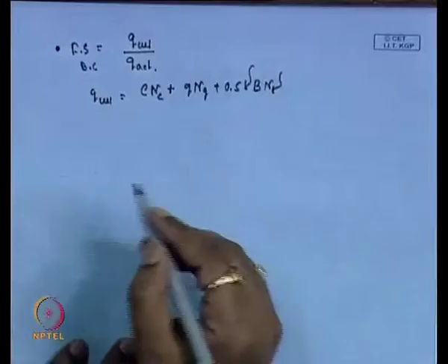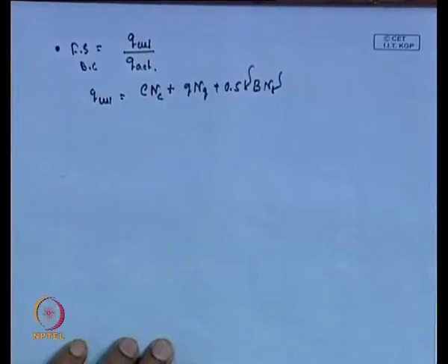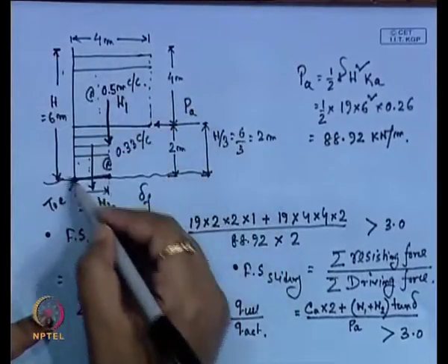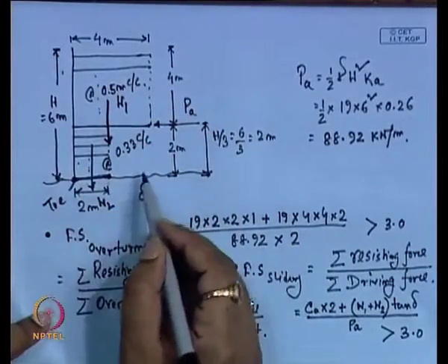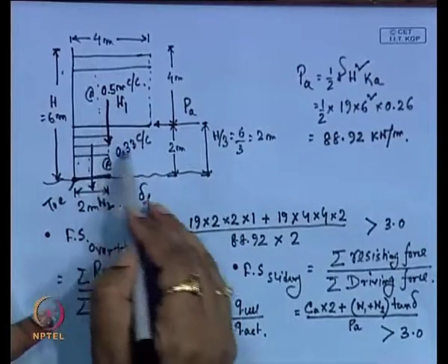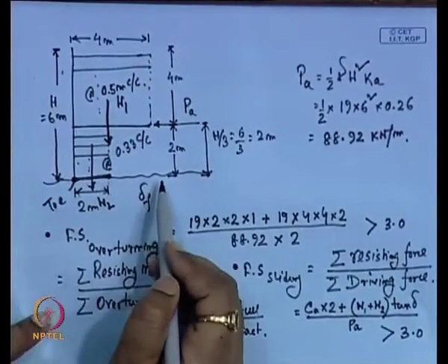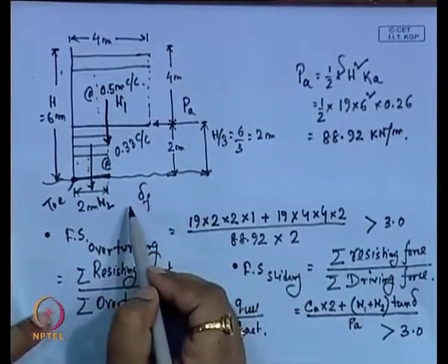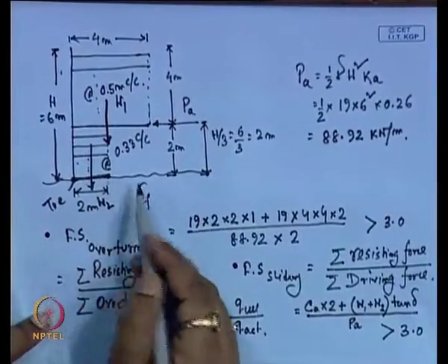and gamma we will consider as the gamma of the foundation soil. Here another thing is mentioned: this will act as a total load of the reinforcement. This is the footing which is resting on the foundation, it is not below the surface. So, here Q value is 0 basically.